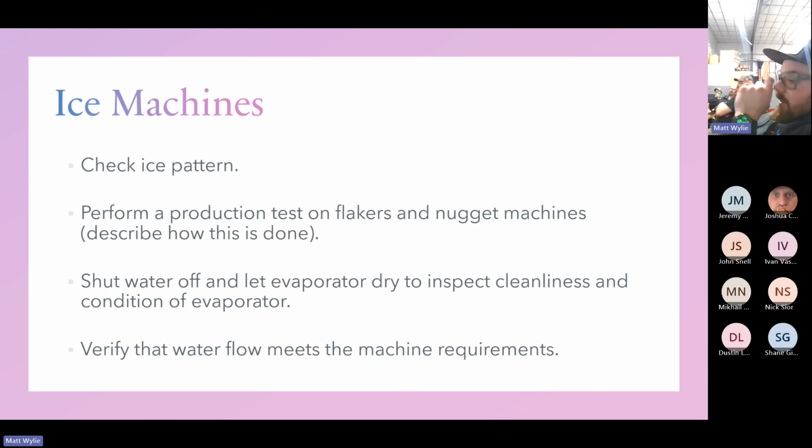If you're at, say, any Costco, or they have the big trays, or one of the big dish pans, put that in and catch the ice. You catch all the ice that falls, and then you weigh that ice, and then you do the calculations of how much that ice should weigh, and whatever that weighs, you times it by their calculation, and then that will tell you how much ice should be dropping in a 24-hour period.